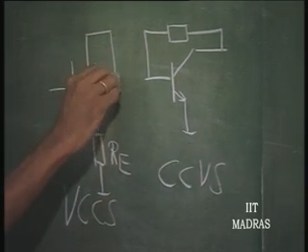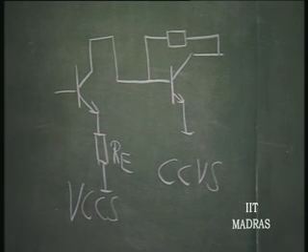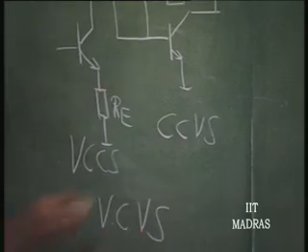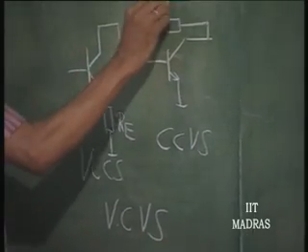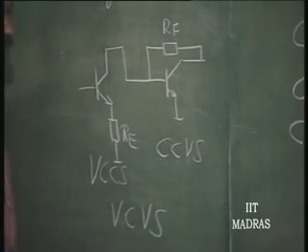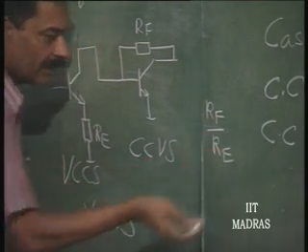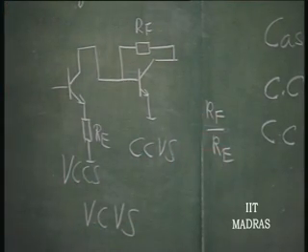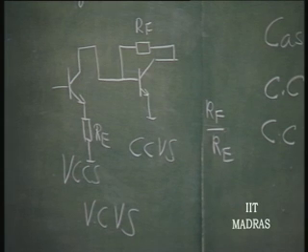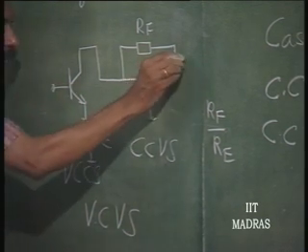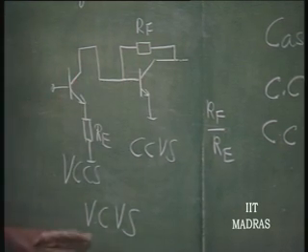By connecting this like this, it becomes a wideband voltage controlled voltage source. This also has been discussed earlier, and the gain of this is RF divided by RE.